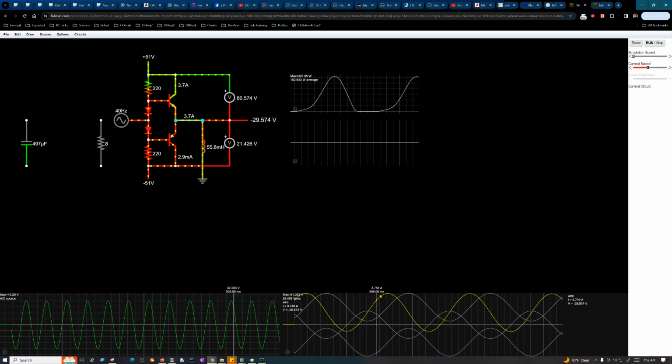But you'll notice that the yellow waveform is our current, right? But it should be balanced just like the voltage waveform is. In other words, you can see it's offset to the top. And the reason is, and I've run into this with capacitor circuits before, usually professional simulators don't do that because they run a transient analysis before they start showing you live data. They get it to steady state before they start showing you. Well, they don't do that on Falstad.